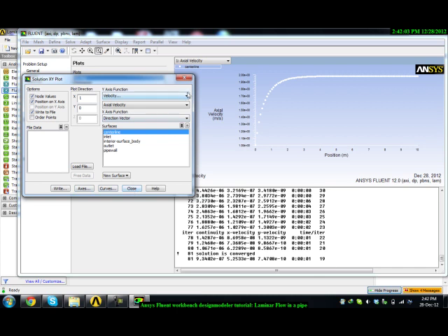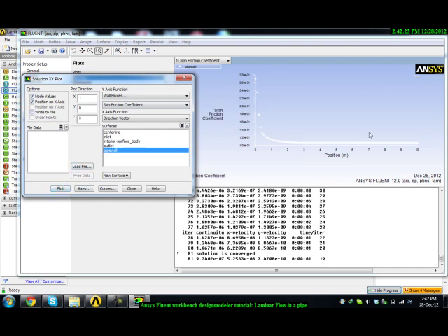And you can similarly go to density, properties, wall fluxes. Let's say you want to select wall shear stress, you go to wall flux and select wall shear stress or skin friction coefficient. Close to pipe wall, and then it should plot the skin friction coefficient.